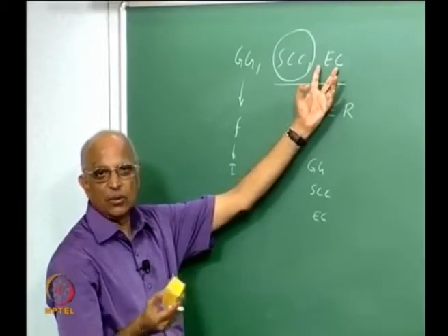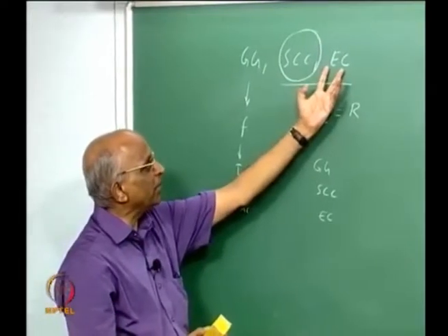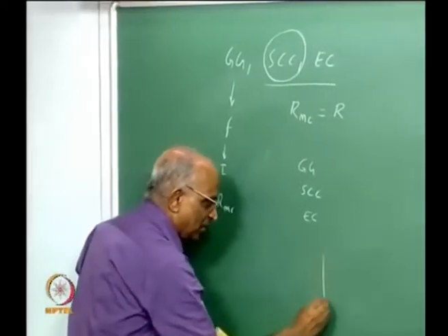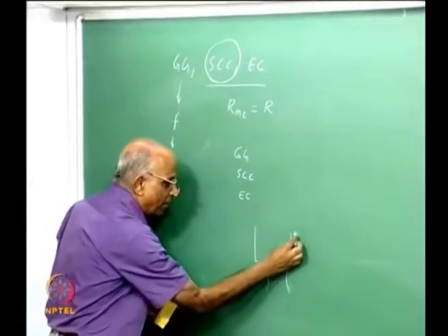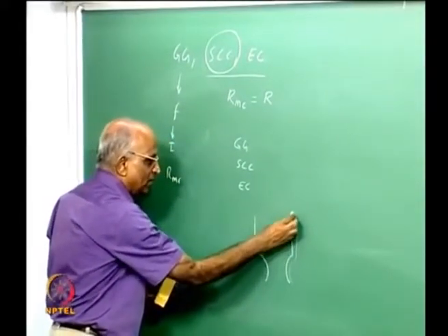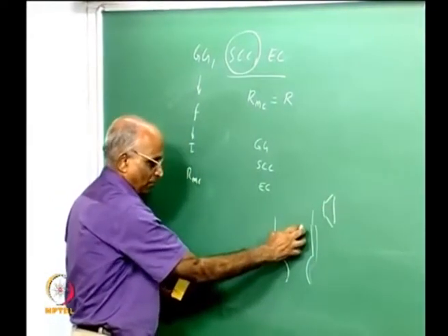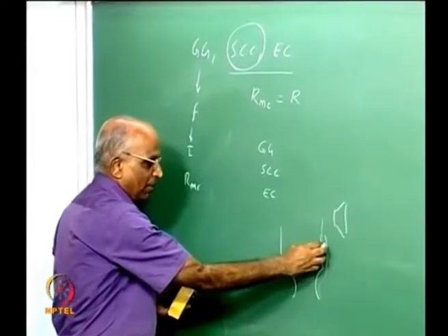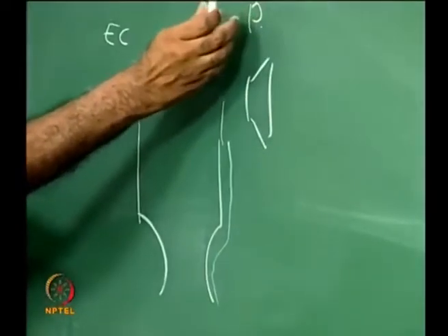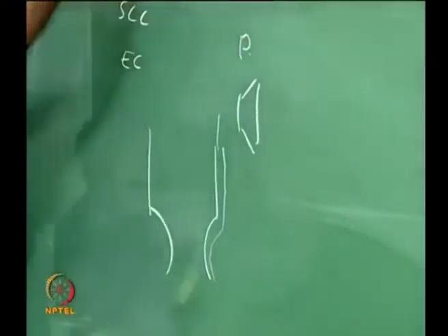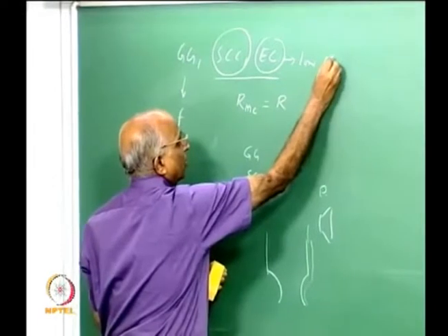Maybe we will take a look at some examples. Why we cannot operate at high pressure in an expander cycle? We are using a chamber which runs hot to be able to form vapor from the gases, and this vapor is used to drive the turbine. I have limited amount of heat transfer in a chamber, and therefore I cannot have very high power, and since I cannot have very high power, expander cycle also operates at low chamber pressures.